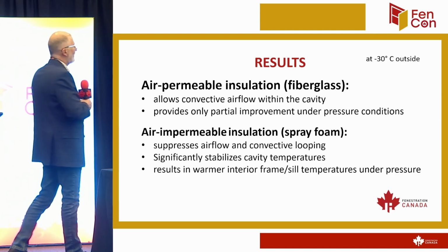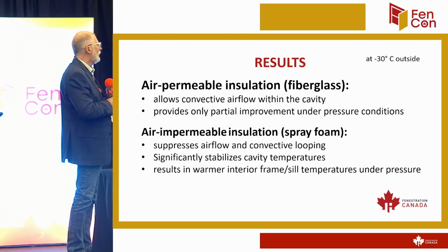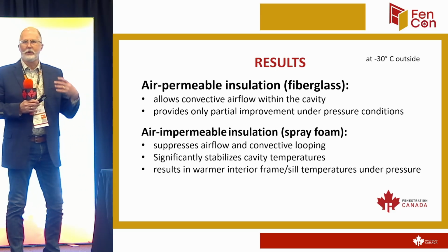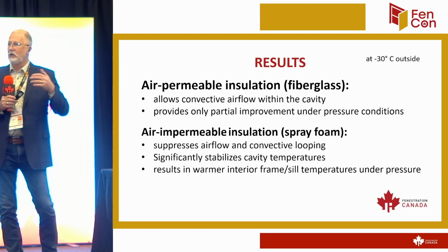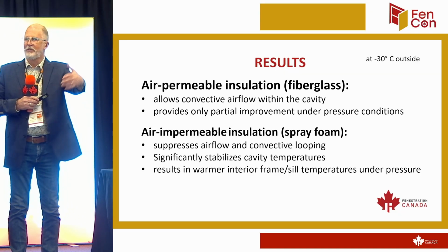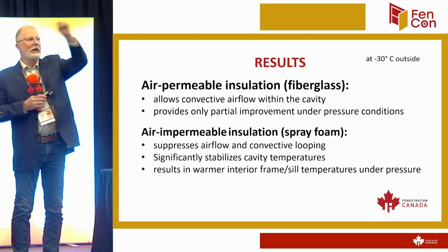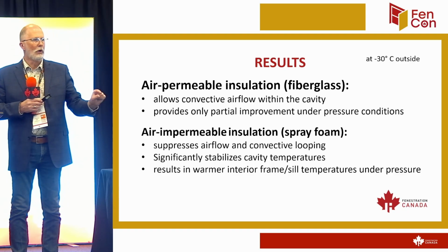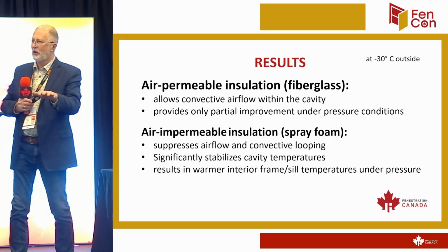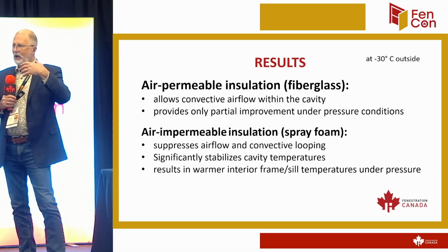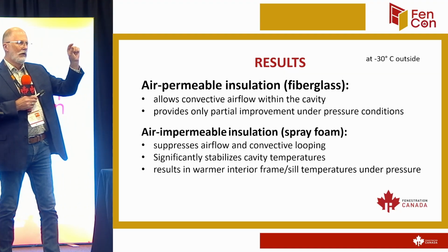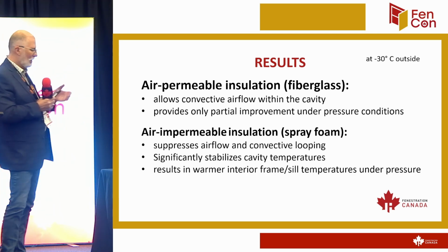So what it tells us is that when you look at these different materials in terms of insulation or no insulation, yes, I'd always prefer to go on the side of insulate the rough opening. But if I take the steps to first of all install the window, seal the outside 3 sides, let the bottom open and drain out, because I put a sill pan in and I let that water escape, then on the inside, I give it a 4-side, really good airtight seal. And that way I can accomplish this.